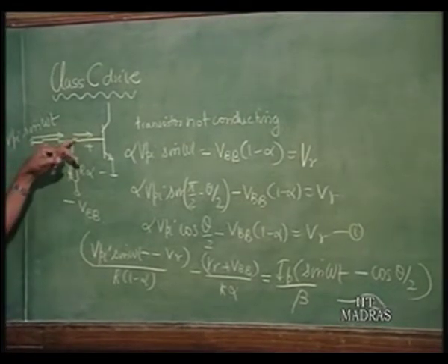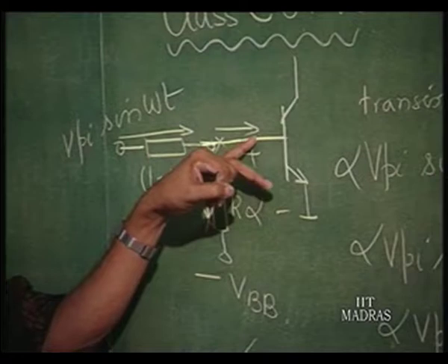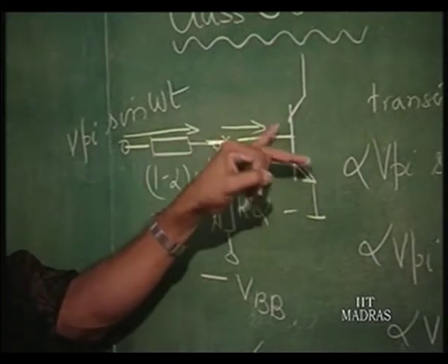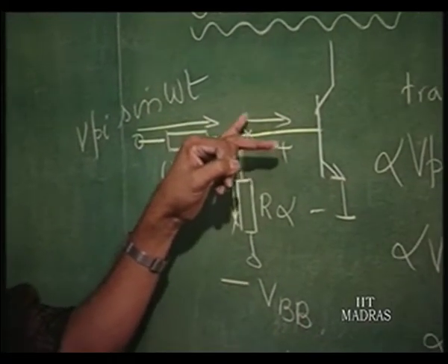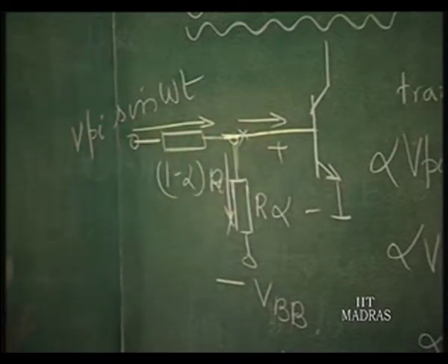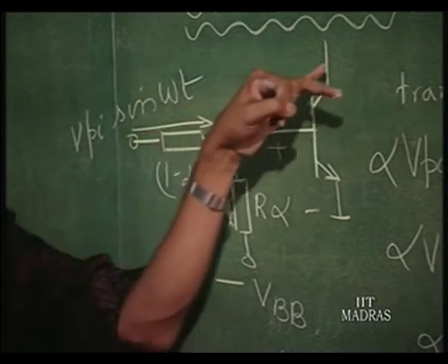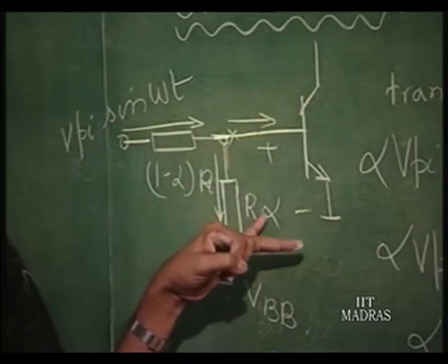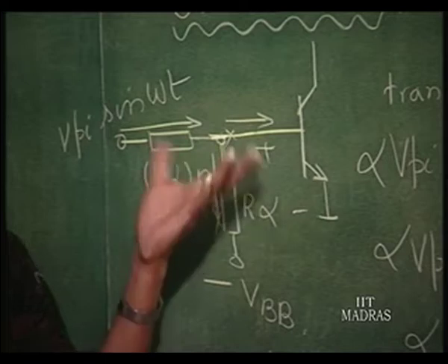There is a maximum base current also, like maximum collector current. For every transistor there is a permissible maximum base current, which should not be exceeded. It is not really always equal to IC maximum divided by beta, it might be more than that. So, that is one thing.